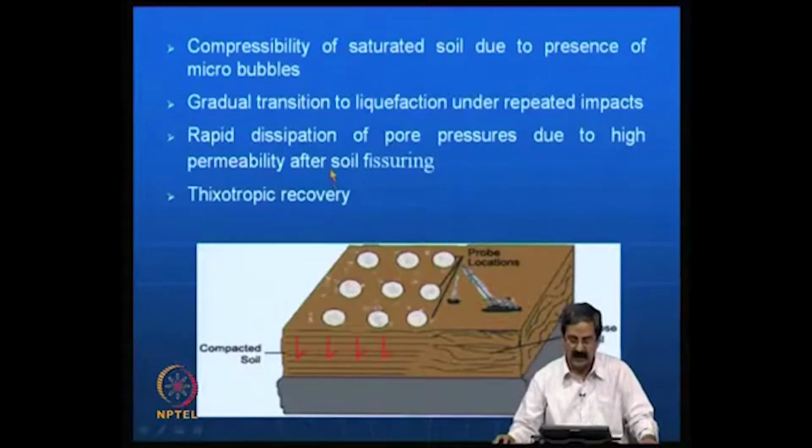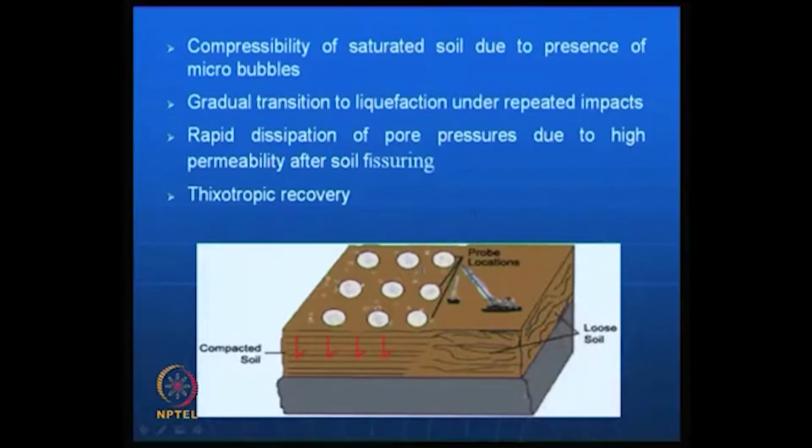So, what is going to happen is that in this case you can see that this is essentially a loose soil, and you have probing locations in this manner, and you compact the sample. As I just mentioned, if you want larger depths you have a wider spacing, and if you want shallow depths you want a closer spacing of the